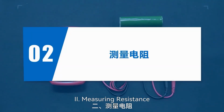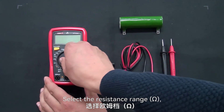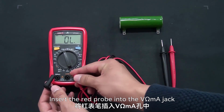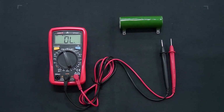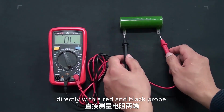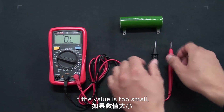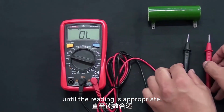2. Measuring resistance. Select the resistance range, with a maximum range of 200 megaohms. Insert the red probe into the volt-ohm milliampere jack and the black probe into the COM jack. Measure both ends of the resistor directly with the red and black probes, and then look at the display area to read it. If the value is too small, for better measurement accuracy, switch to a smaller range until the reading is appropriate.